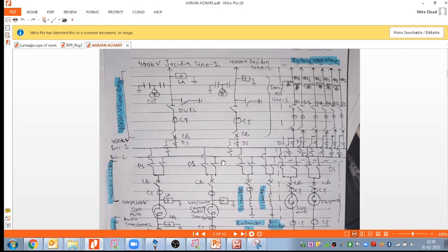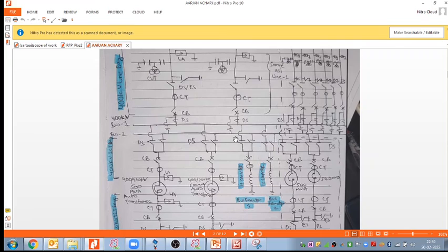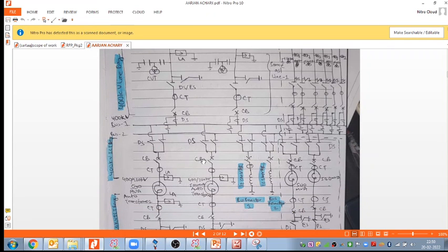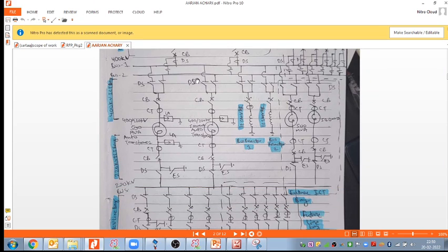Okay, but we will discuss later whether we should put two buses like that, because in 400 kV we will follow the 1.5 breaker scheme, so that will be a different kind of structure. This structure will change, and I will explain how it will be. But yes, you have applied your mind that there will be two buses because of two reactors, that is perfectly correct.